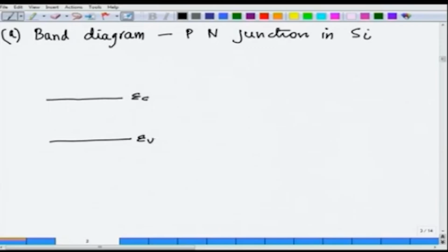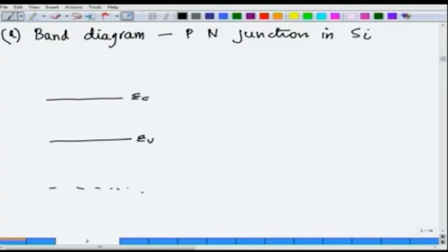Now, we are going to choose a reference energy. In lecture number 16, you will recall we had chosen different kinds of reference energies, when I was talking about donor levels and acceptor levels. Because energies always appear as differences, some energy minus another energy, the reference you choose cancels out, but nonetheless all energies must be measured to a common reference. There I chose a reference energy arbitrarily as 0 somewhere here, then moved on and chose EV as the reference energy.